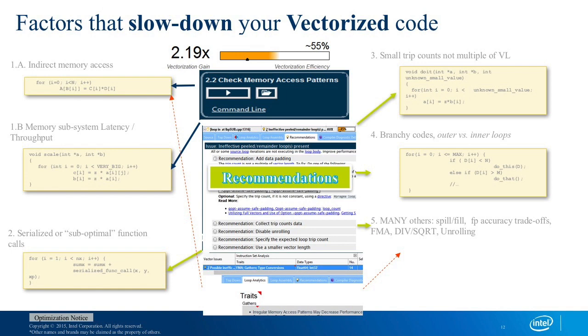Then you get the trip counts and the flop counts, which will be added to the same display that we saw before. Then we get another column for the flops and for other stuff that has been added. And if you want to take a snapshot, there is a knob, or you can do it with the command line as well.